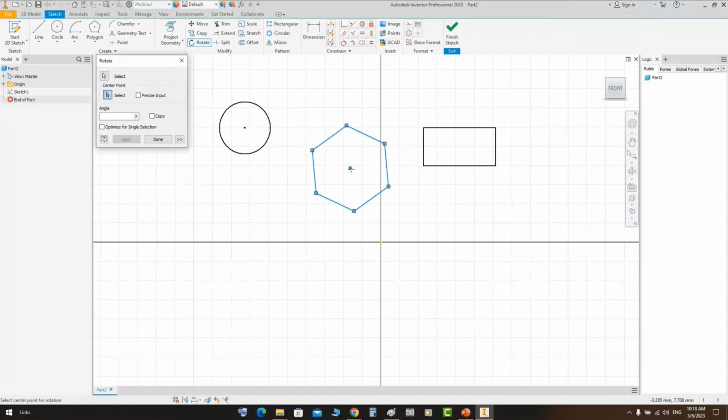So you will rotate this polygon from the center, or rotate it from one of those edges. Let's select one of those edges, or another outside edge here. Let's select this one. So we will rotate all of that around this point, for example. When you select this point, automatically you can rotate this one, and the value will appear here. So you can define your value in this text box. Let's make it 50 degrees. So the orientation will be like that. Let's increase it a little bit. Let's make it 90 degrees.